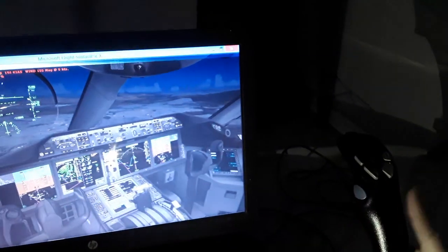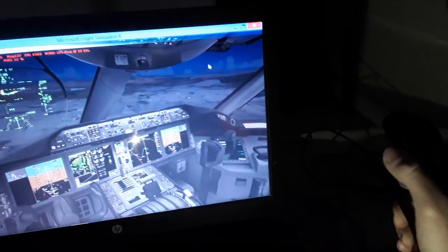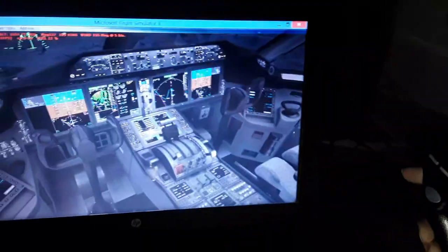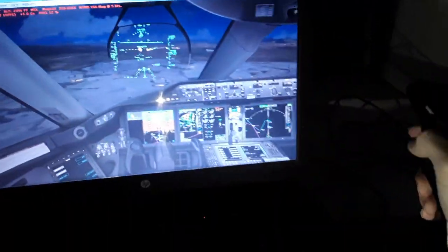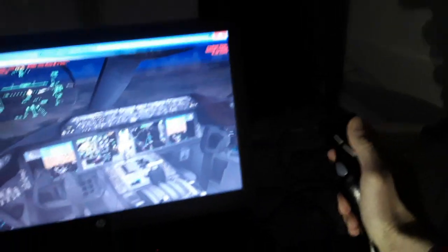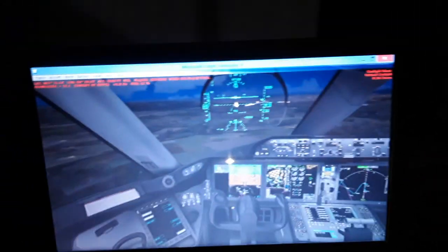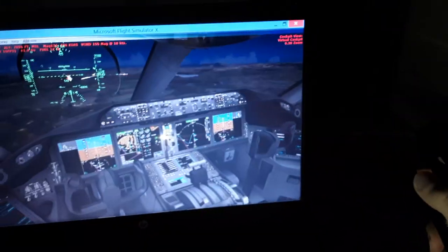Add some thrust right now, a bit of airspeed, we need airspeed. And also some flaps. We need 1 more minute for approach and landing. So you can see the localizer also. The glide slope, we are inside the glide slope. And also the horizontal localizer, so we have some side wind, a little bit, not too much right now.